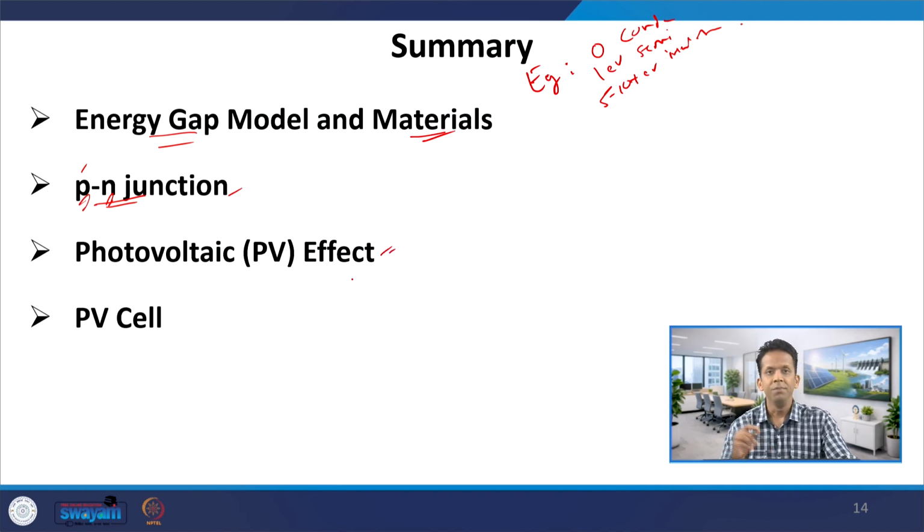We looked at the definition of the photovoltaic effect, which is the conversion of light into electricity using a solar PV cell composed of a p-n junction. We saw how the energy from photons of light is captured by electrons, which get excited, and electron and hole pairs are formed. Those charge carriers move towards opposite ends: electrons move towards the n-type material and holes towards the p-type material. Once the circuit is completed, there is a current flowing through the cell.